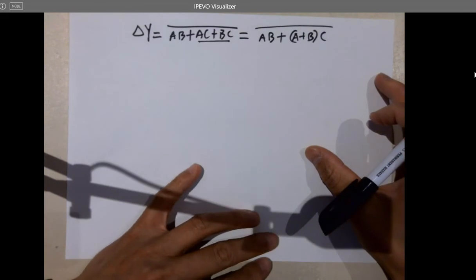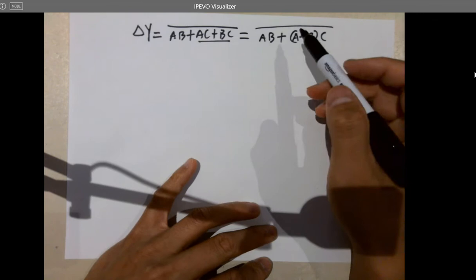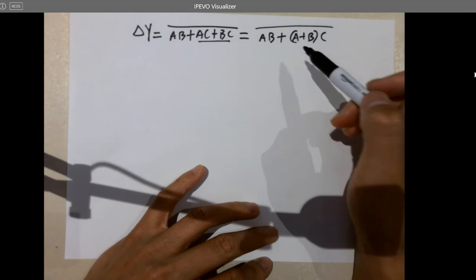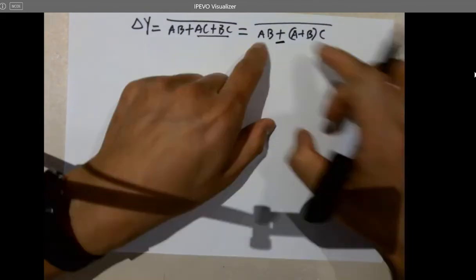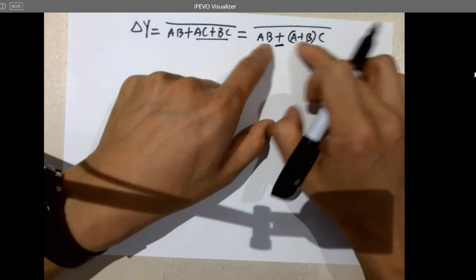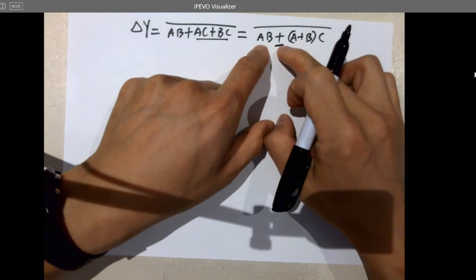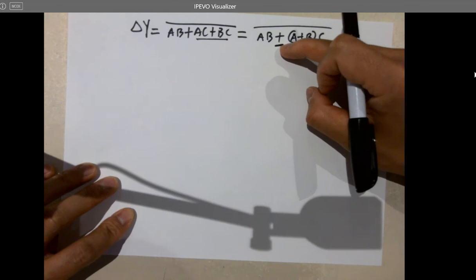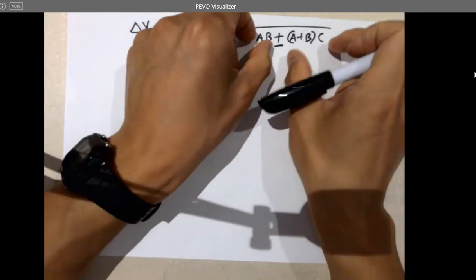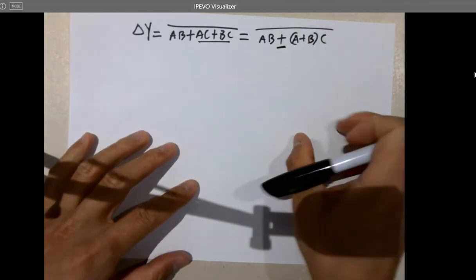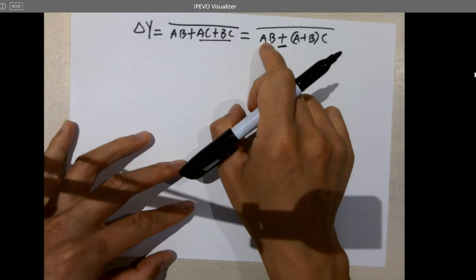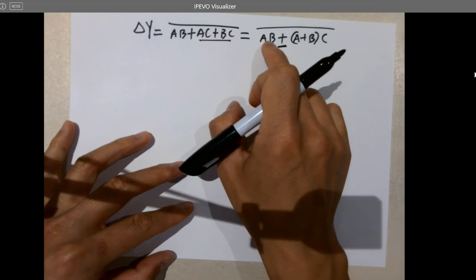And what's next? So we have this structure now. Now we can start working on converting this to its complex CMOS logic circuit. That's the overall operator, the final operation. So you got two black boxes to be NORed. They're being NORed together. So you need these two boxes in series on the top and parallel at the bottom. But internally, these A and B should be in parallel.